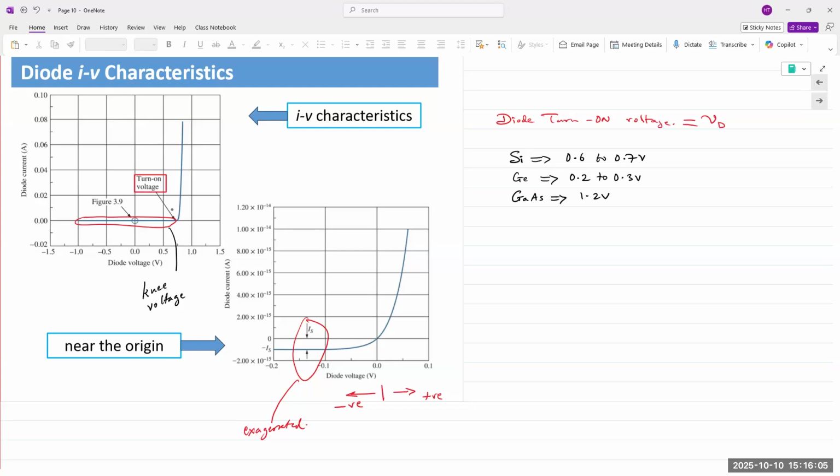Okay. So when we use the silicon diodes, we use sweep and go. Did everybody use sweep and go in the other labs also? Yes, no? At least I know in my labs it worked. Fine, okay, great. So sweep and go is a great software. Now you can compare and contrast how long it took to take the manual characteristics versus an automated one. Right? So with the LEDs, requires more than 1.2 because the barrier, the depletion region is slightly wider.